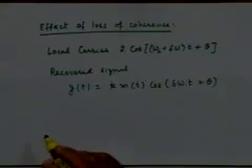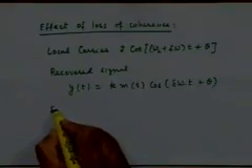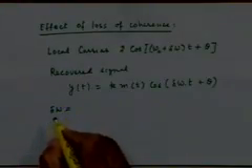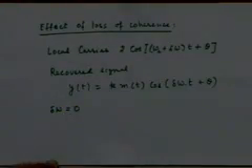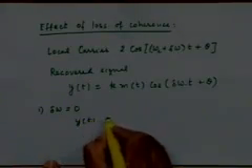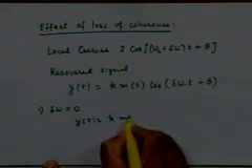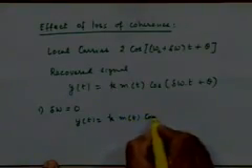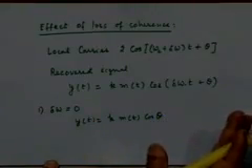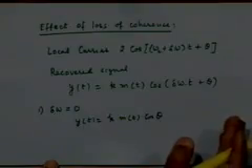To appreciate what this output is like, let's simplify the discussion first. Assume that there is no frequency perturbation, that the frequency at least is perfectly synchronized. So let's say delta omega is 0. Case 1 where delta omega is 0. Now what will happen? So y(t) would be k times m(t) into cosine theta. Seems alright, isn't it? Because cosine theta is also a constant.